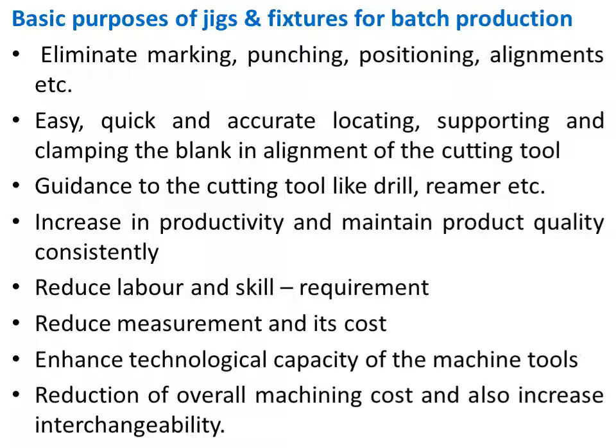The next point is reduce labor and skill requirement. You need not have a very skilled operator if you use a fixture for the purpose of making the hole on the part. Then reduce the measurement and its cost, because the measurement is already made and the hole is accurately drilled onto the component. There is no need of measuring again and again on all the n number of components. So this is a large reduction in cycle time as far as the components are concerned.